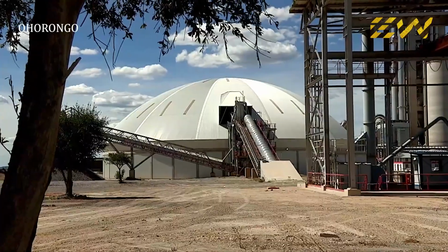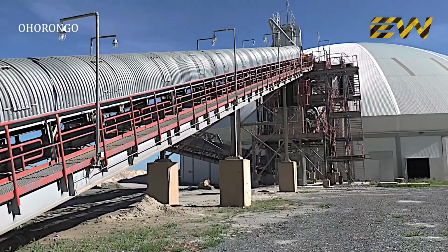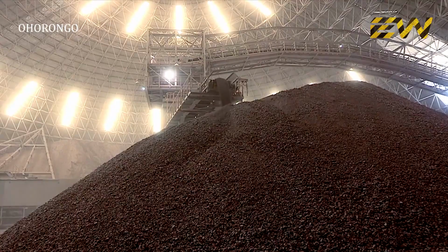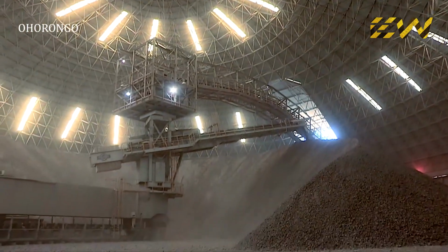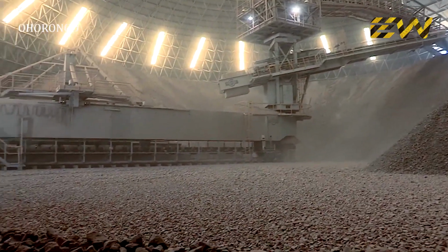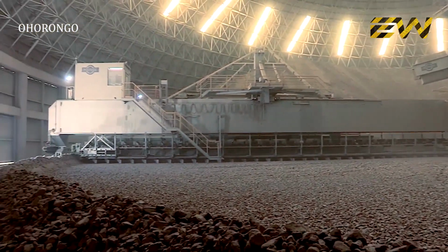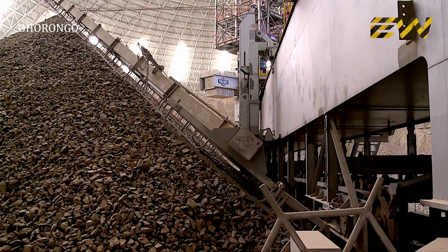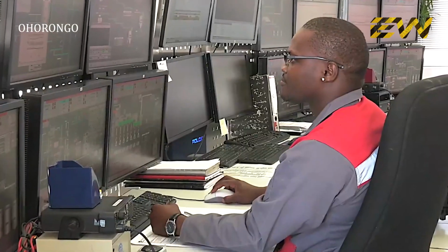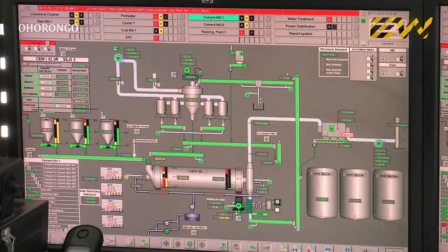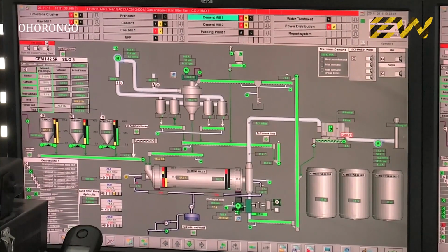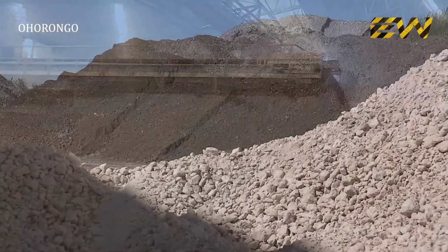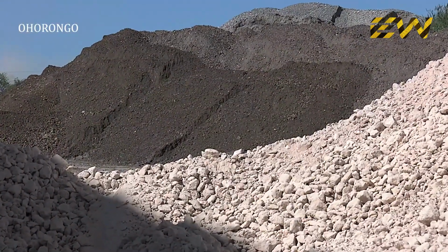The crushed limestone, shale, and marl are conveyed to the mixing bay, where it's mixed to a homogeneous material. The homogeneous store has a radius of 81 meters and a height of 28 meters, and has a blending bay which can handle 25,000 tons of mixed materials. The chemical composition of the material is carefully monitored to ensure that it contains the correct proportions of raw materials. A small proportion of corrective materials are added to the mixture if the proportions differ from those specified by the quality department.